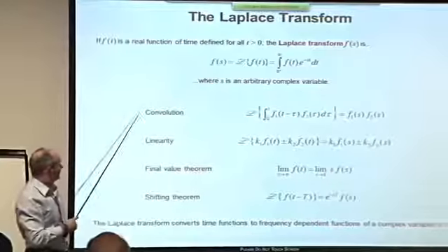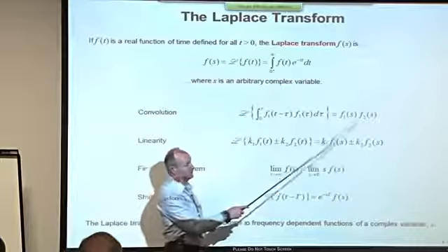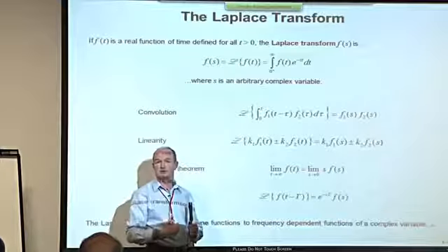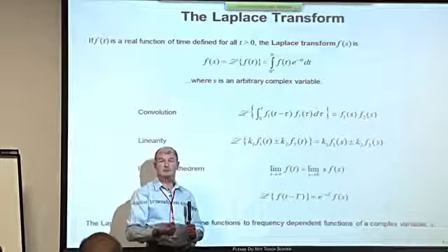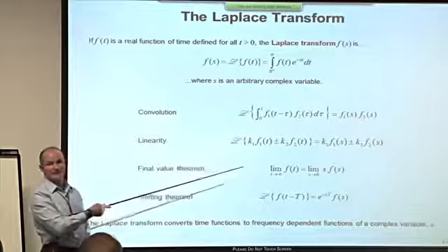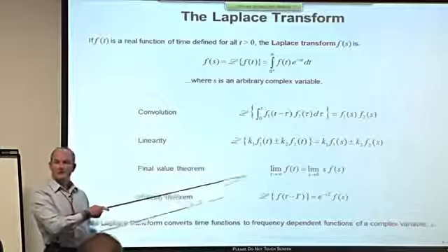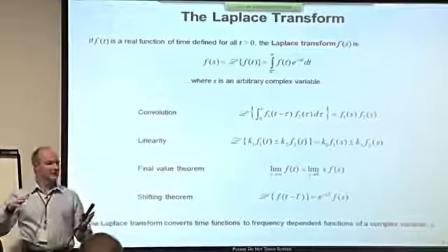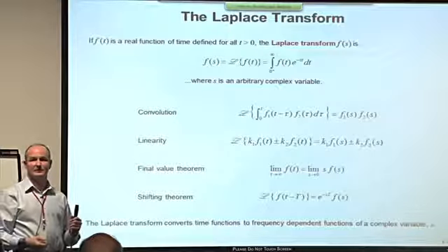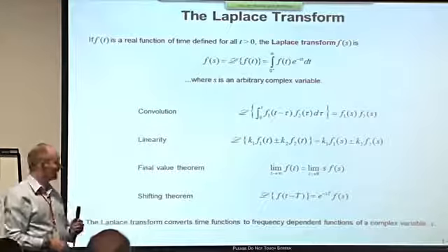The first is that it has a property called the convolution property. It replaces that convolution integral with a straightforward multiplication. So if we can take the Laplace transforms of the things we're interested in finding out about, all we've got to do is multiply them together. The second property is, well, who recognizes it? It's superposition, right? It's a linear transformation. So the fact that this is a linear transformation makes it possible to combine signals in parallel paths, as we might do in a PID controller, for example. The Laplace transform is quite feasible to simply add Laplace transforms together in a situation like that.